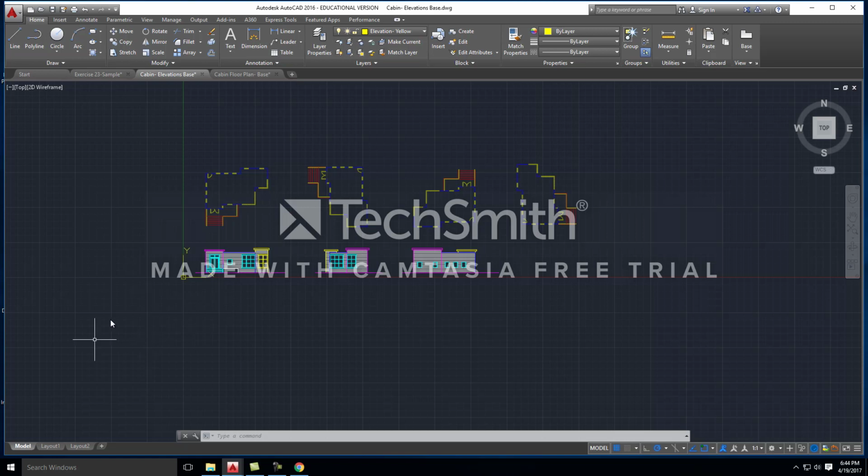As we transition into Paperspace, we're going to learn how to transfer the information that we have here in model space down into another work area. If you go down to the very bottom left-hand corner, now you can barely see this on the screen, but you're going to see two tabs that say Layout 1, Layout 2.